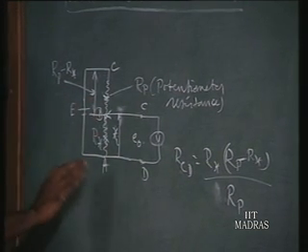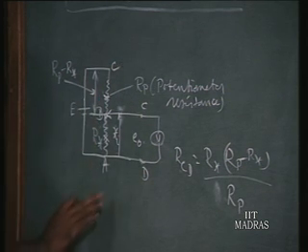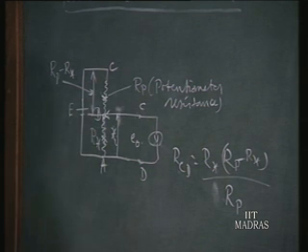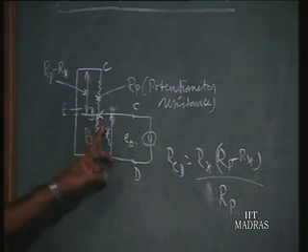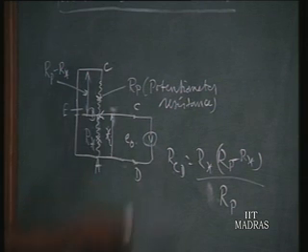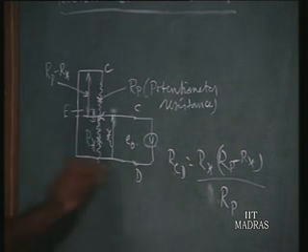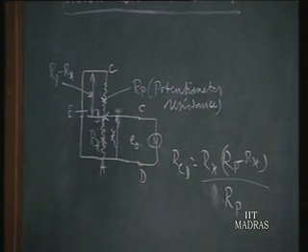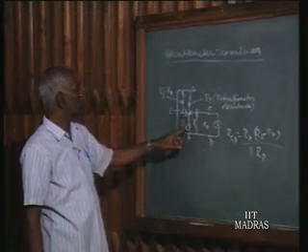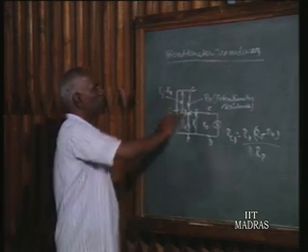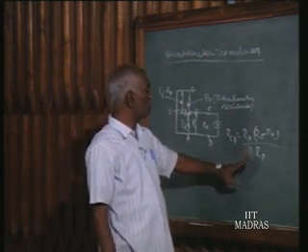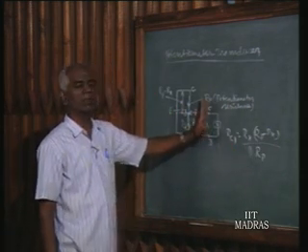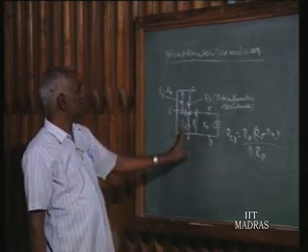But the main point to note here is, in a potentiometer transducer, where the potentiometer circuit is used for transducing a displacement to voltage, we have got a varying output resistance. This is the important point. Hence the loading effect also will be varying. That is sufficient now to know about this circuit. Later on, when we take up some problem, you will see how to make measurements when there is a varying loading effect. We will go to the other circuit.